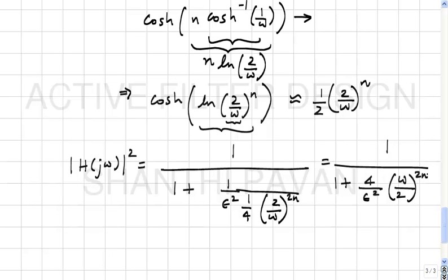Which means that when you flip and flop and all this other stuff, in the pass band it must monotonically approach 1 at DC. This also indicates that around DC, this is as good as the Butterworth. So clearly, the pass band is as good as the Butterworth.